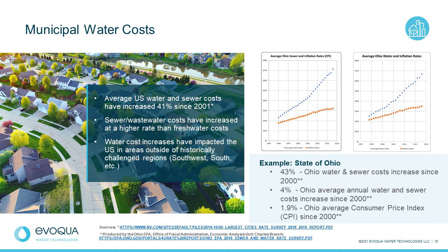More stringent drinking water and wastewater regulations have driven much of the increased cost in regions that have abundant water supplies. The requirement for higher quality effluent from water reclamation facilities makes water reuse more attractive, as little additional processing is required, depending on the ultimate use. It's not unusual to see treated wastewater effluent with lower turbidity, a measure of clarity, and organic content, that is purity, than the receiving stream.